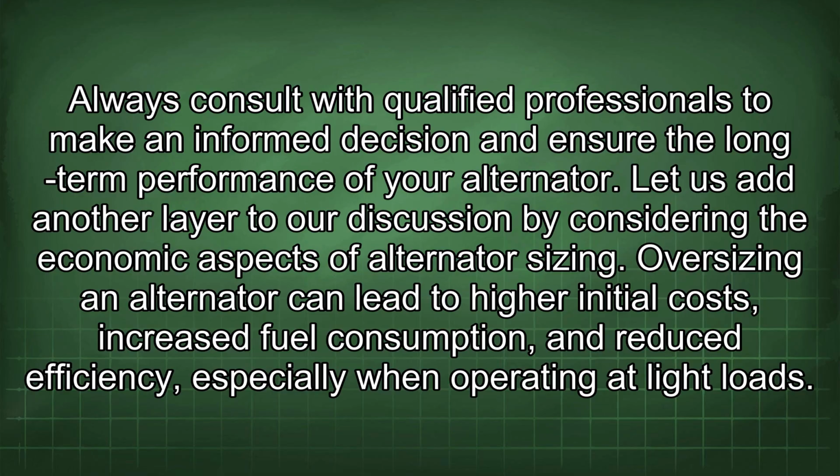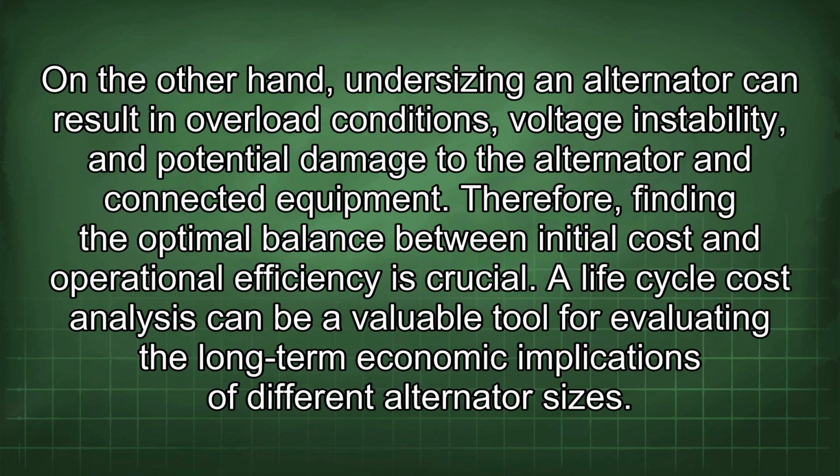Let us add another layer to our discussion by considering the economic aspects of alternator sizing. Oversizing an alternator can lead to higher initial costs, increased fuel consumption, and reduced efficiency, especially when operating at light loads. On the other hand, undersizing an alternator can result in overload conditions, voltage instability, and potential damage to the alternator and connected equipment. Therefore, finding the optimal balance between initial cost and operational efficiency is crucial.